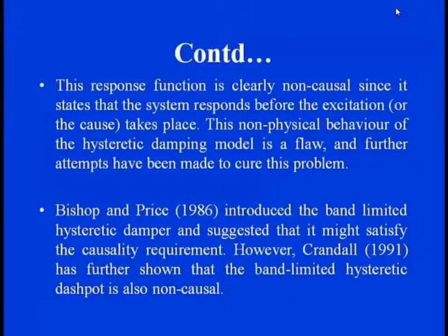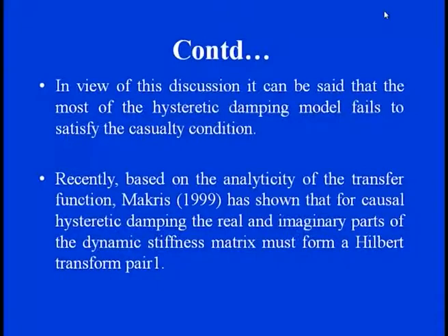And then Crandall in 1991 adopted those features and added that a band-limited hysteresis dashpot is non-causal. So what I mean to say is that in all this discussion, most of the hysteresis dampers fail to satisfy the causality conditions, which is one of the requirements of damping.